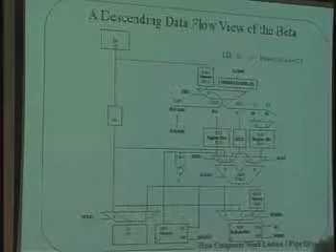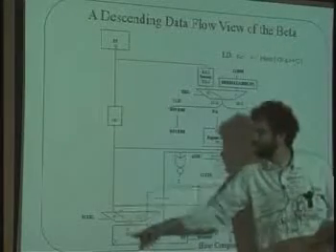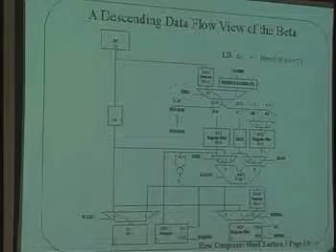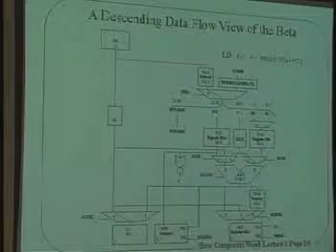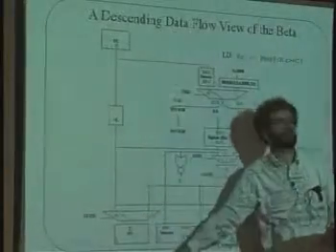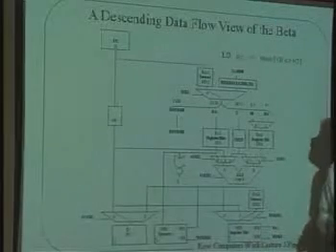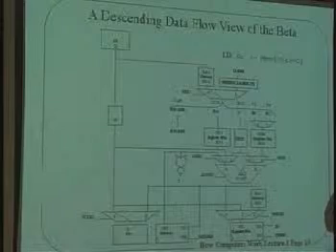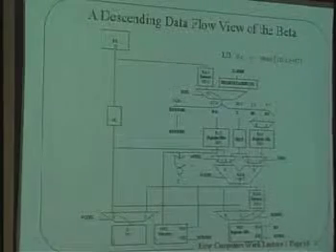The PC gets one added to it and gets overwritten, so that the next PC is going to be the next opcode after a load. It's not a branch, right? So anything that's not a branch will always choose this path, and the updating of the PC is a straightforward thing. The actual execution of the load, however, is kind of neat.